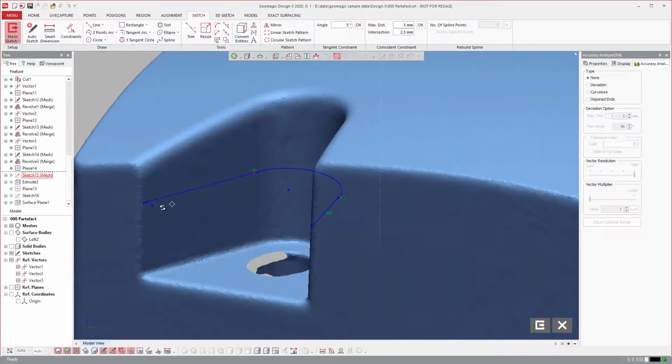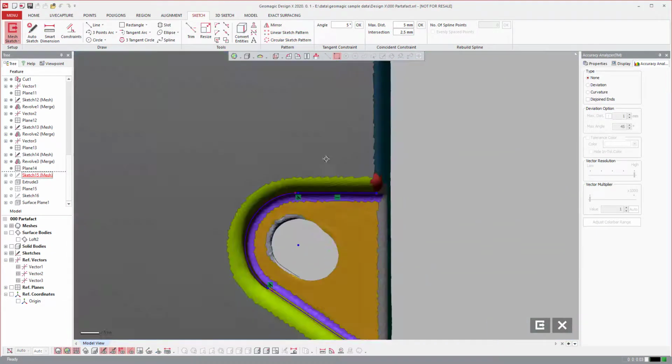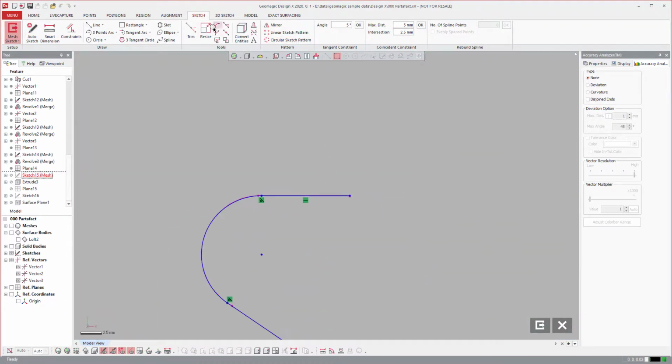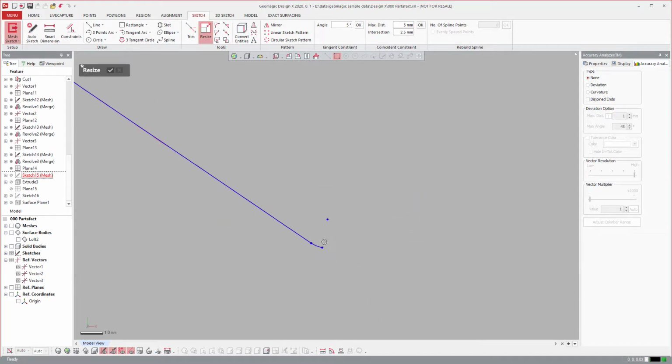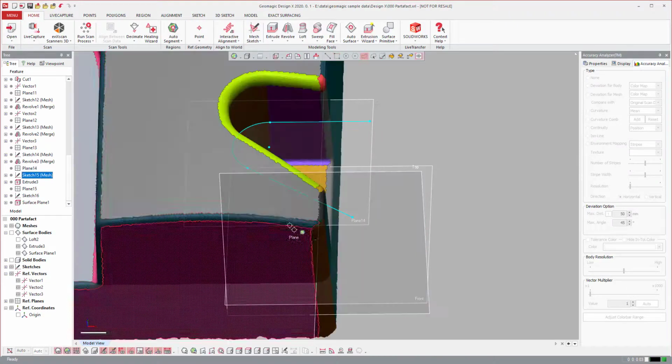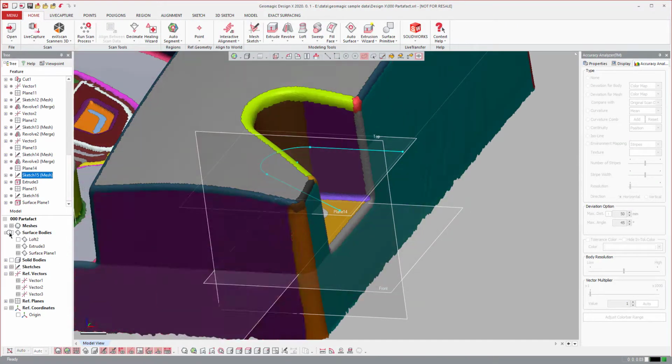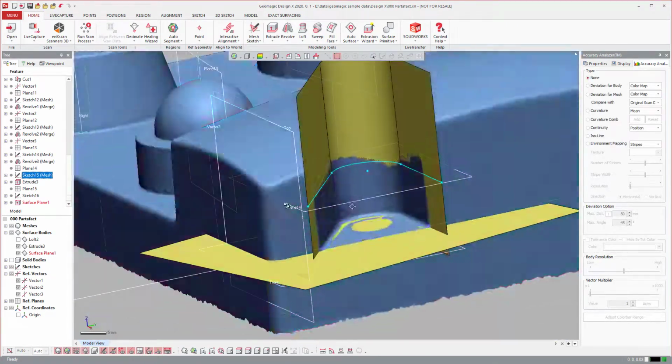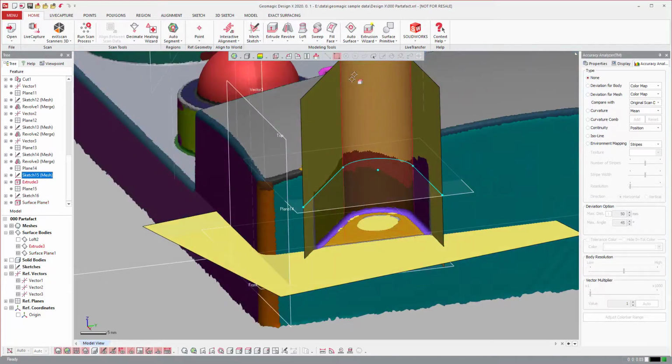if I want to make any changes here, I can just go normal to that plane, and resize these and extend them. This one I want to make a change to, so I'm going to go ahead and remove that little fillet on the end and resize that to extend past the other surfaces that are there. Now if I get out of it and turn my surfaces on, you'll see those two surfaces that are there. So I can model it this way too.